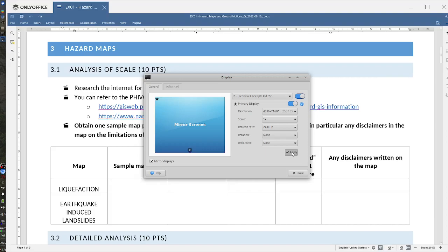The age: faults that are younger than Pleistocene. Usually Pleistocene is the cut-off age for active faults, or approximately 10,000 years. So faults equal to or younger than 10,000 years are considered active.